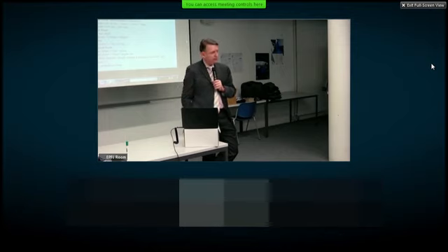RF power, so microwaves. Transmitting or transferring power through microwaves is becoming, of course, we've had microwave ovens for a long time, but even doing power beaming over larger distances with microwaves is definitely something that's been demonstrated, and there's a lot of interest in it. Here also we have pretty standard frequencies, so 2.4 gigahertz, 5.8 gigahertz. You have a whole industry built around these standards.